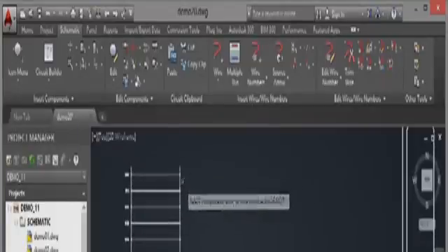Now you've got a wire coming down here on your ladder and then you've got your rungs here. So you've got the two wires, that one there, that form the ladder, and then you've got the rungs going across. So if I click on this wire here, you'll see the Scoot command kicks in and I can move that visually wherever I want to. But you'll notice that the dynamic input automatically goes off because the Scoot is a visual thing. If I come down here, I can't touch the status bar. Scoot is tying me to the screen. So if I go this way like that, I don't know actually how far I've moved it.